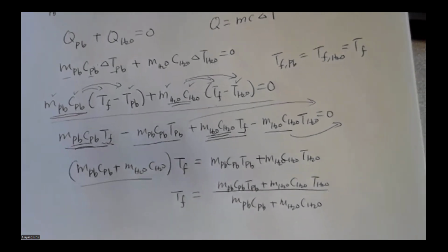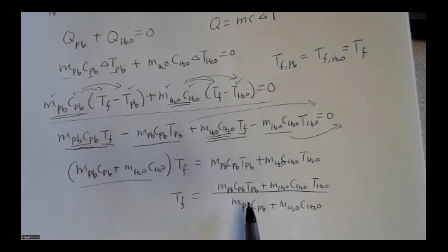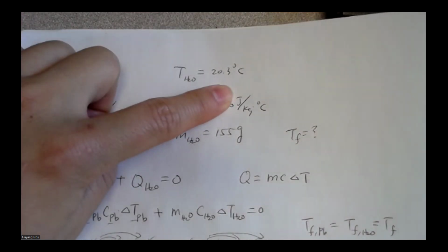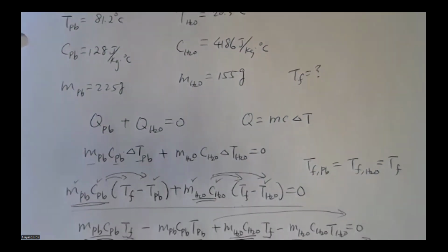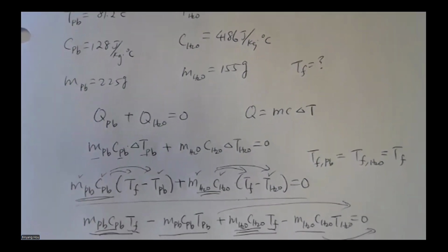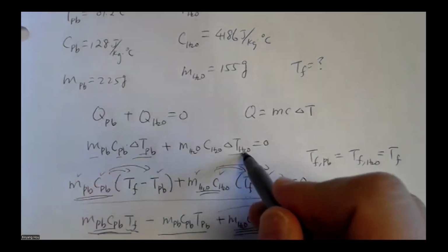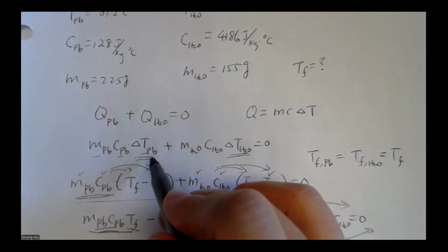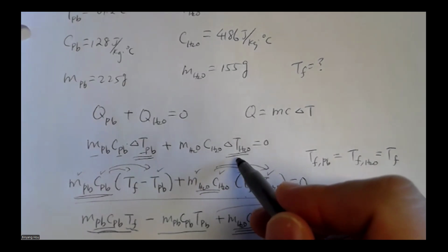Okay. And now, normally you think that you need to convert TPB because it's given as Celsius, right? Not Kelvin. Kelvin will be the SI unit, and this one is Celsius. You might want to convert into Kelvin, but it actually is not necessary because here we are using delta T. Okay, so we know that delta T, the change in temperature in Kelvin and change in temperature in Celsius, they are the same.